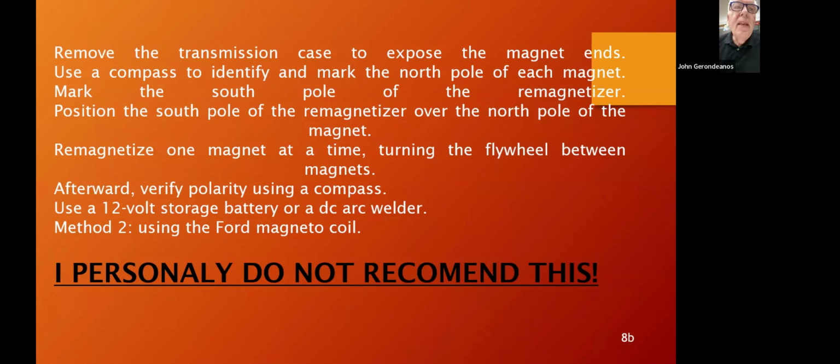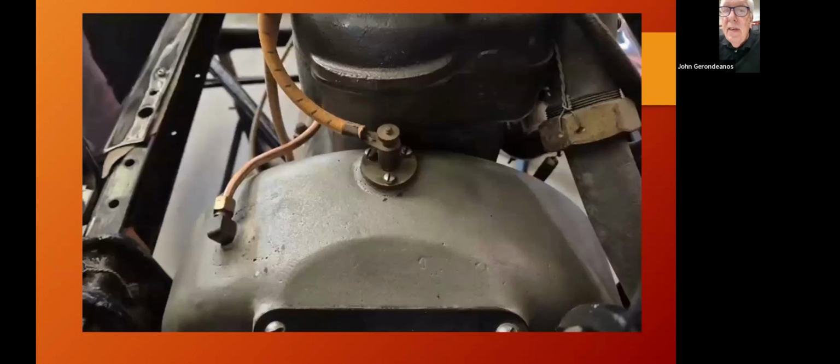being poor and the insulation being poor, the chances are that you're going to damage your magneto coil, either short it to ground or make it open circuit. Anyway, this is the method. So you have to, and this is now with the car fully assembled, nothing taken off, access the top of the hogshead, and disconnect the cable from the magneto at the hogshead. So there's the hogshead. You disconnect the cable from there.